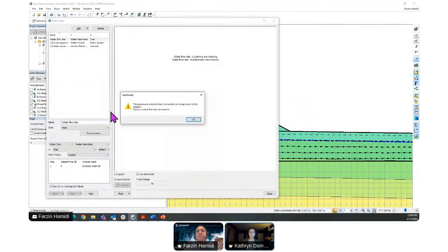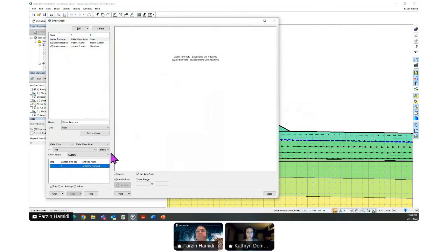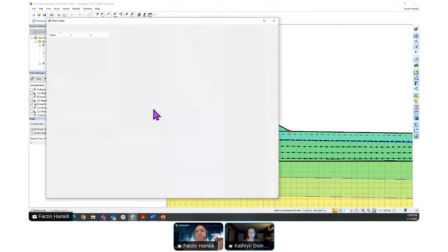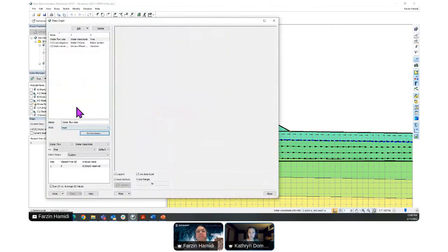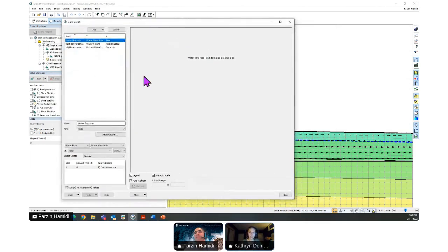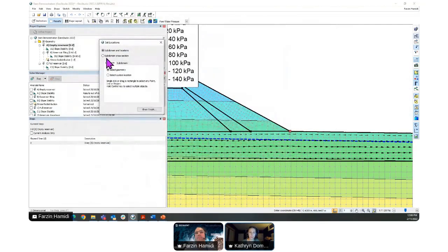So say the dam that you're modeling is actually 50 meters long, then you just simply multiply that flow value by 50 meters to get the total flow that you would be seeing through your dam. So that's just a quick way to assess if you're trying to provide an initial estimate for flow through a dam cross section. That would be how you would do it. I don't ever play around with the out of screen dimension in GeoStudio. I just leave it as that unit width, so it's a lot easier for calculating things. If you wanted to add a certain length to them, you just multiply by that length. You don't have to worry about what that out of screen dimension is in your model.